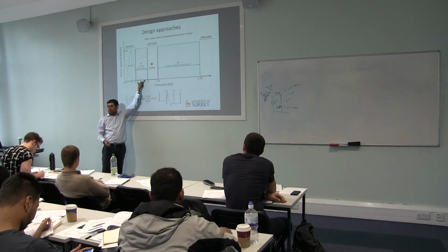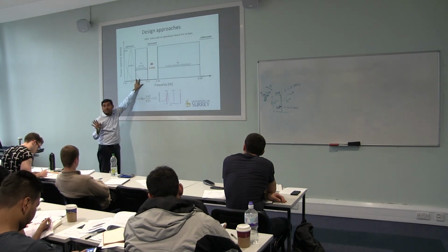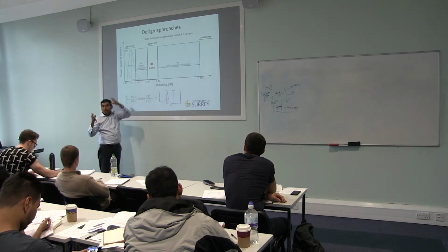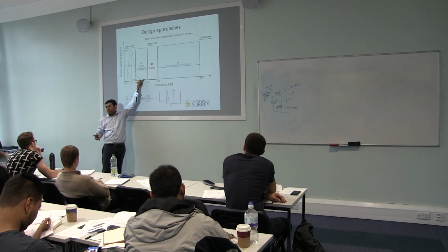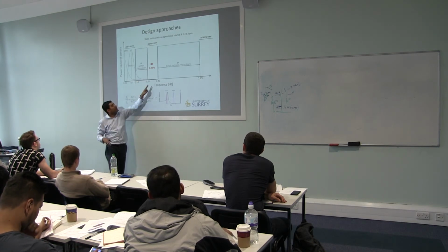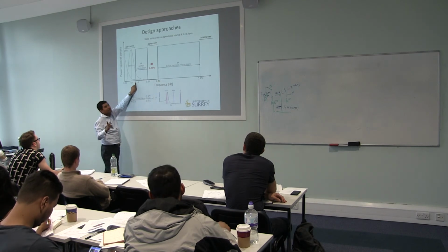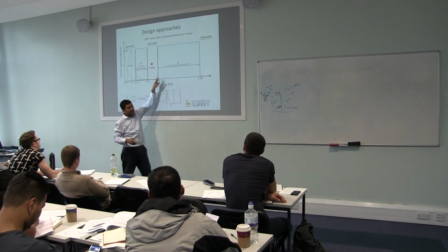So this is a function of the wind turbine you chose, its characteristics. Go to the brochure, find out the cut-in and rated speeds, and you get this range. If it is 3-bladed, you get 3P frequencies. How? 0.14 times 3 is 0.42, and 0.31 times 3 is 0.93.